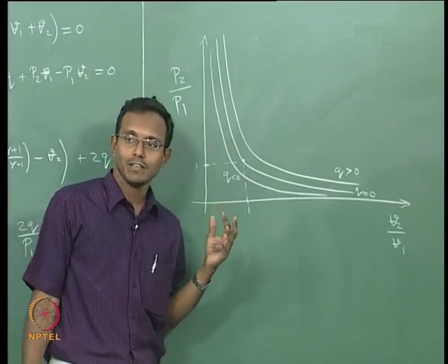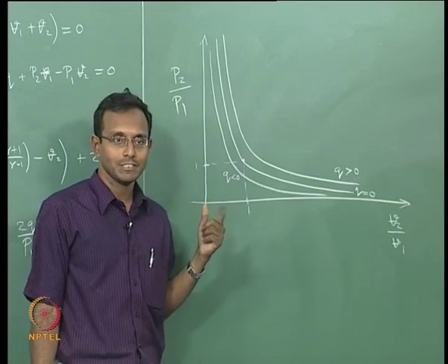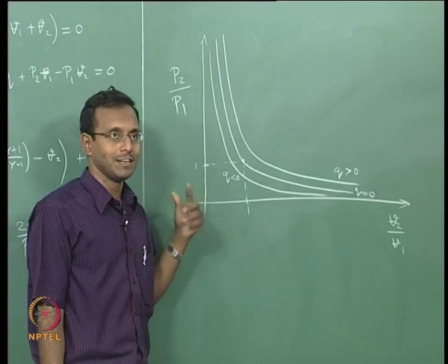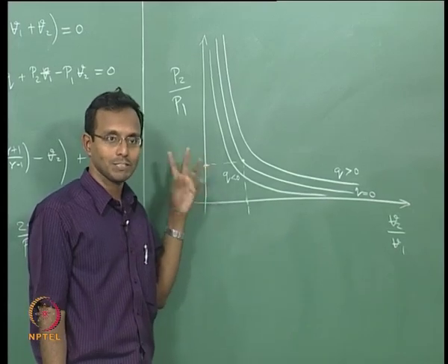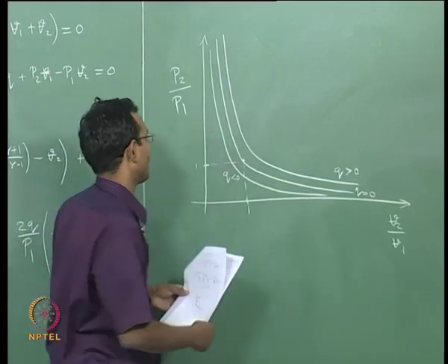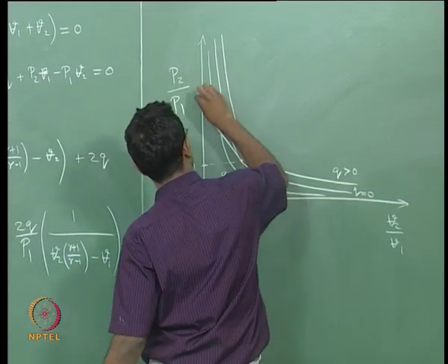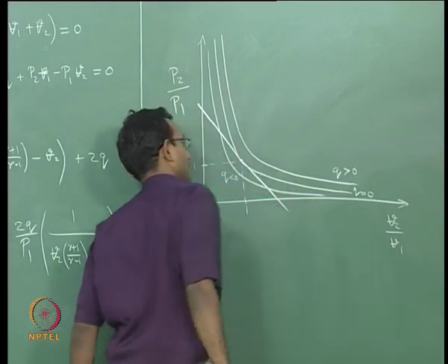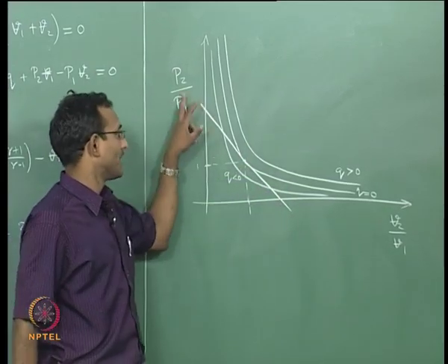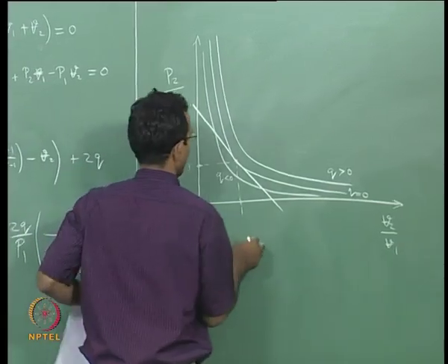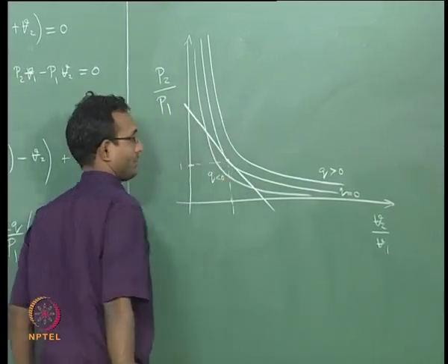will satisfy mass, momentum, energy, state, and the previous one will satisfy mass, energy and state for this one, and mass, momentum, energy for the Rayleigh line. From here I will draw the Rayleigh line also, say for a particular M1. For a particular M1 if I start with, it is going to be some curve like this. So, my final solution has to be an intersection of these.